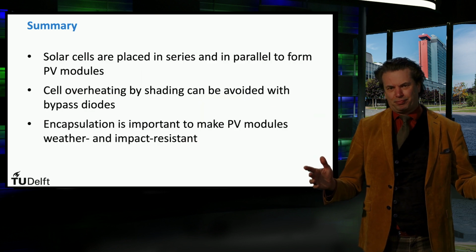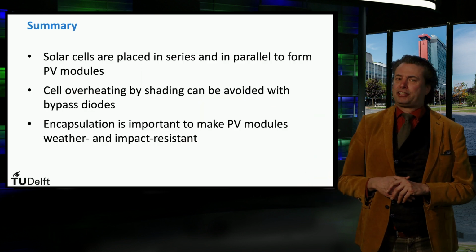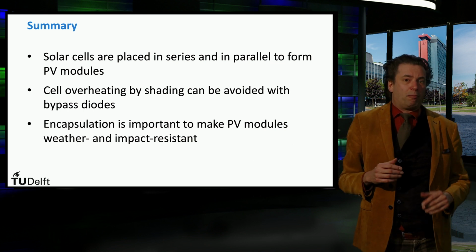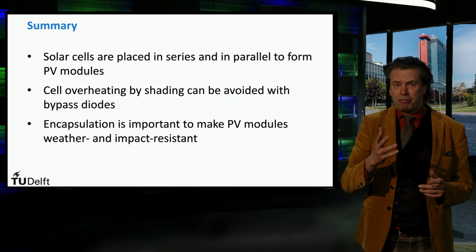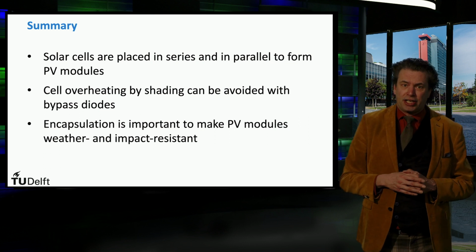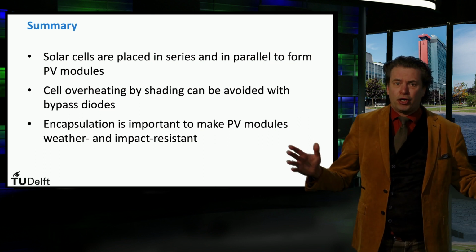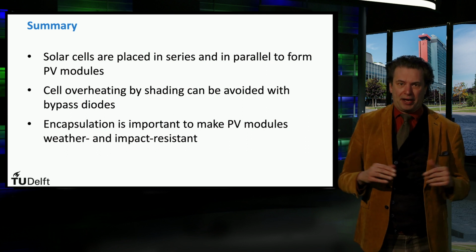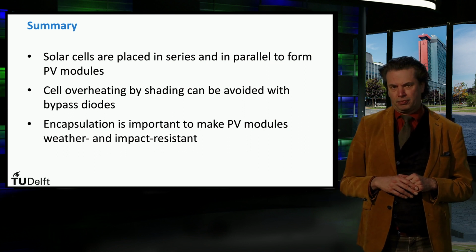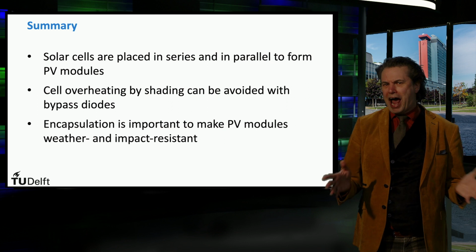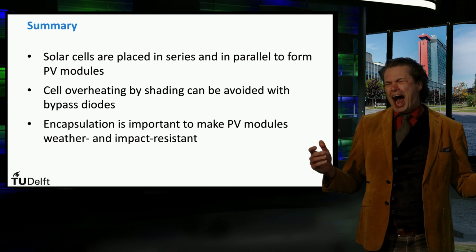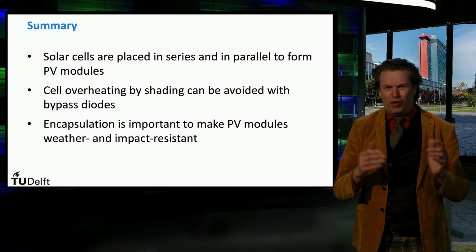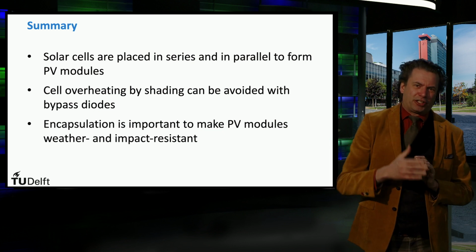In summary, solar cells are placed in series and in parallel to form photovoltaic modules. Cell overheating by shading can be avoided with bypass diodes, and encapsulation is important to make PV modules weather and impact resistant. So this week, we have discussed crystalline silicon wafer-based PV technology. I hope it was a helpful introduction into this technology.